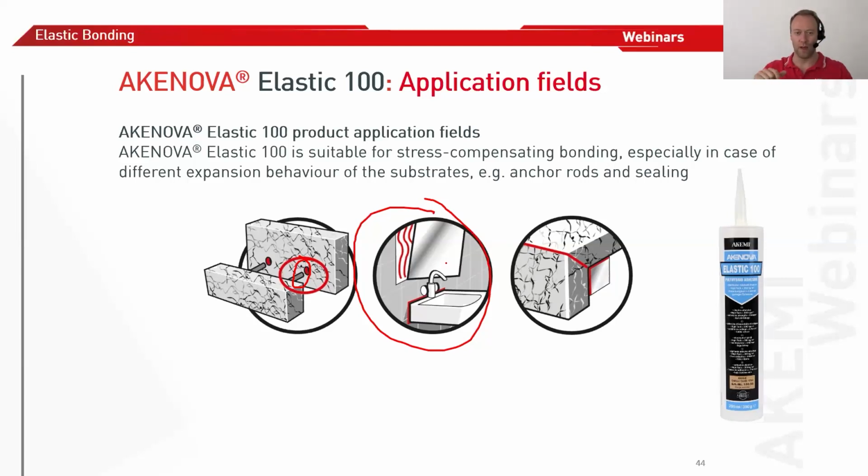Because if there is a lot of water or moisture behind the mirror, it will just run down and will not stick behind the lines, as it would if you put them horizontally. Just as a tip. It doesn't have to be a mirror. It can also be a picture or some stone installations in areas where there's a lot of air and water. Then do the lines from top to bottom.